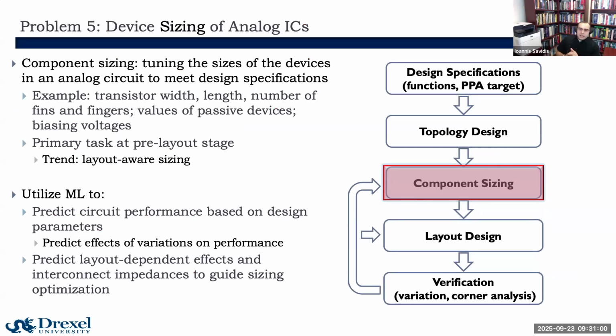So component sizing in analog circuit design is crucial, as we know, to meet the design specifications, and involves adjusting parameters, including the dimensions of transistors and the value of passive devices. This process is typically performed in the pre-layout stage. However, more recently, layout-aware sizing is increasingly being utilized, which basically considers the potential interactions between components earlier in the design phase.